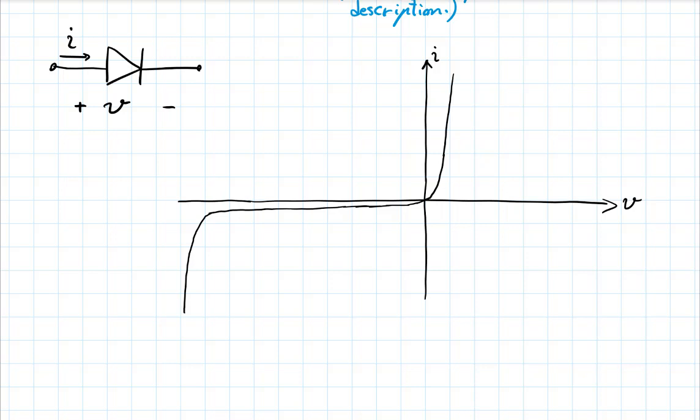And you can put two types of impurities in this, and that gives it a sense of polarity. So you can create an N-type semiconductor, something that has impurities that add more electrons to the system. You can create a P-type semiconductor, something that has impurities that constrain electrons or steal electrons from the system. And if you put these two together, you will form a diode, because you create a charge distribution in space that will block the flow of electrons. And it will behave very differently if you apply a voltage one way versus the other.